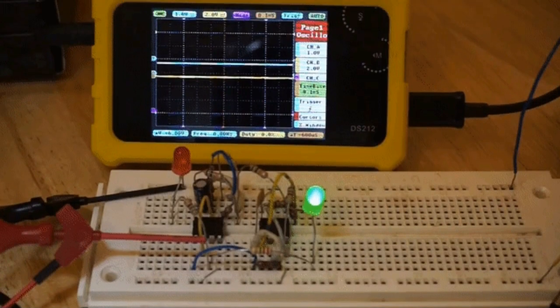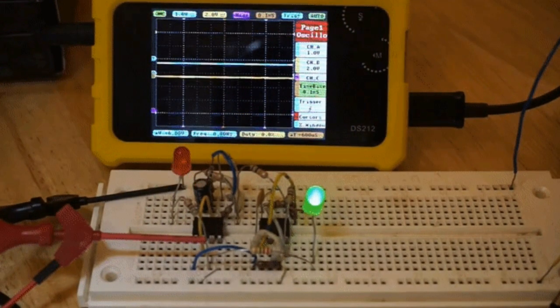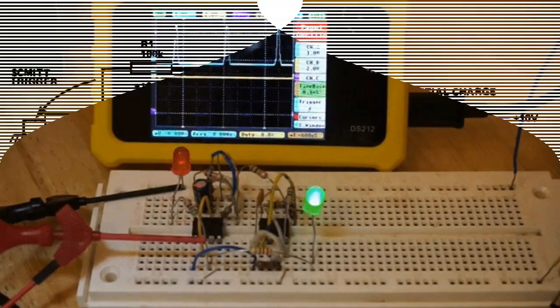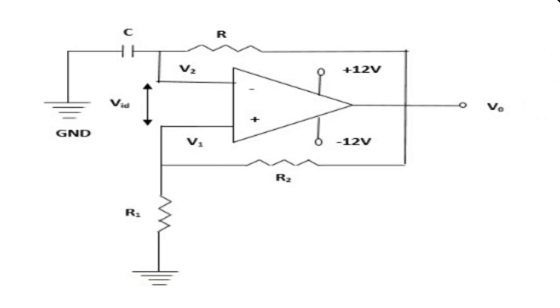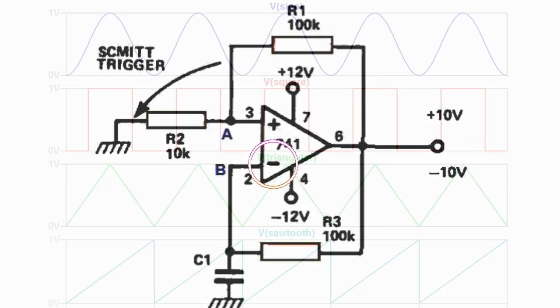The op-amp oscillates immediately as soon as feedback is employed across its non-inverting input and tweaked to the appropriate amplitude. The IC becomes particularly important in resistance-capacitance-tuned oscillators, because its total gain becomes perfectly suitable to offset the attenuation of the RC network. Additionally, the double input of the differential IC enables not only positive feedback for oscillation, but also allows negative feedback in a few circuits for enhancing the output waveform.